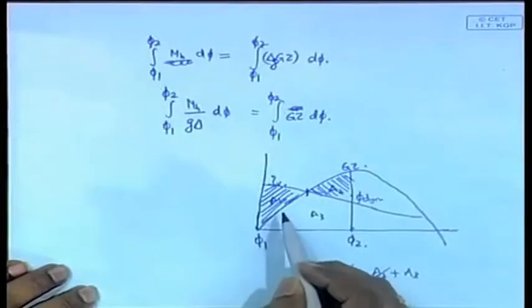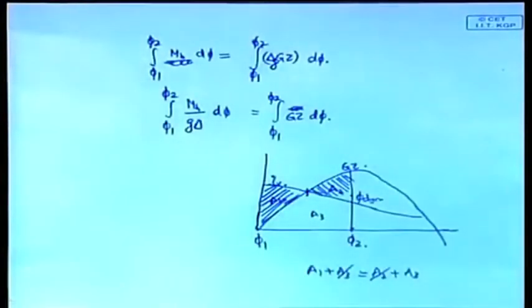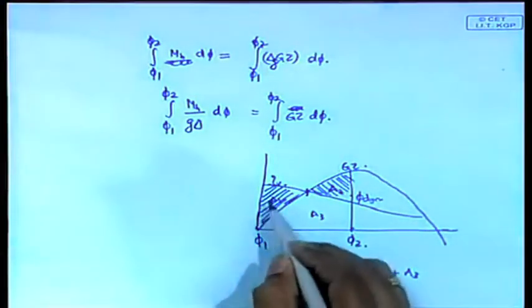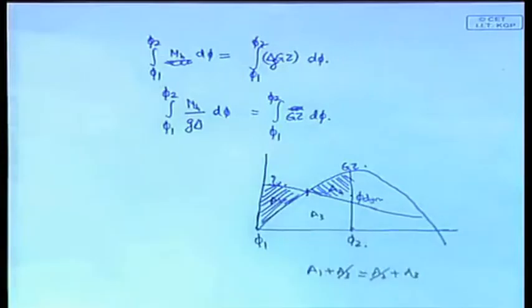That is because there is a difference in area. First of all, some work is done by the heeling moment on the ship, that is the area under the heeling arm curve, then work is done in resisting it. That excess work done by the heeling on the ship is given to the ship, like an energy given to the ship.